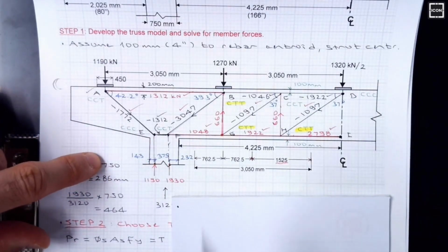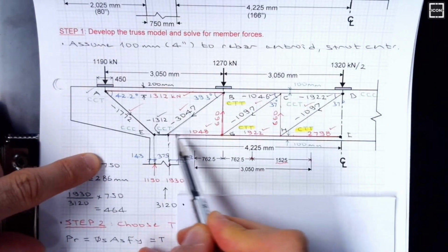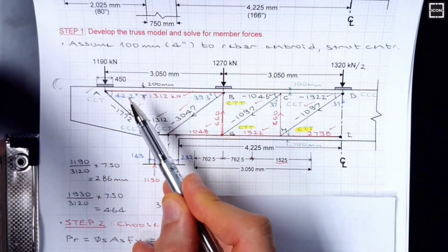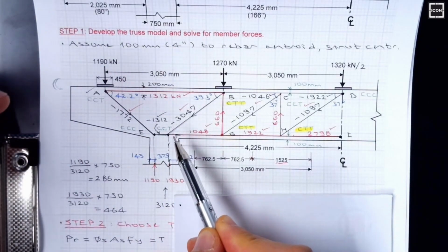The second explanation, you don't want a central node. You want to shift the node as much as to the left or as much as to the right to optimize your angles, because that's how the stress will behave. Stress will take the shortest path. For that reason, that justifies those two nodes as my second explanation.